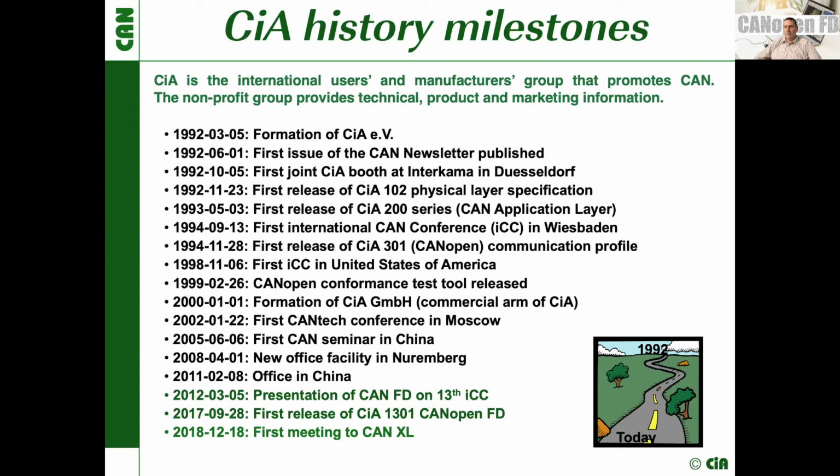And we have here also a working group that is already working on the third generation of CAN, the CAN XL, CAN frames with extended data lengths, up to 2K of data they can carry in one frame, but this is some future. For the moment in silicon, you can get classical CAN or CAN FD. And this is also the base for our day, where CANopen FD stacks are intended for.